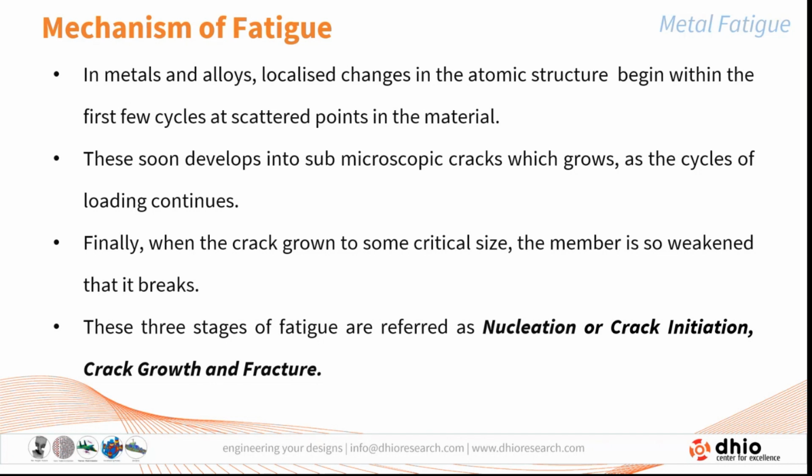Whereas in the case of fatigue loading, the stress distribution across the thickness is going to be different, and thereby the weakest atom is going to behave in a different way when compared to the strongest atom. And this weakest atom is prone to the initiation of the crack.